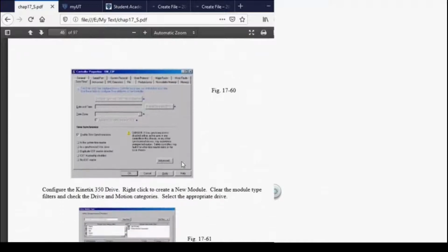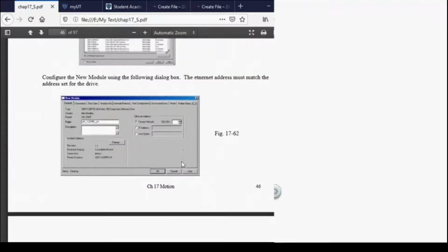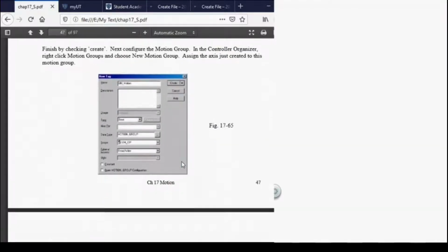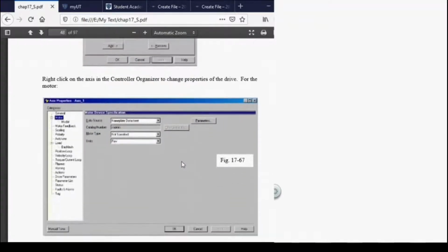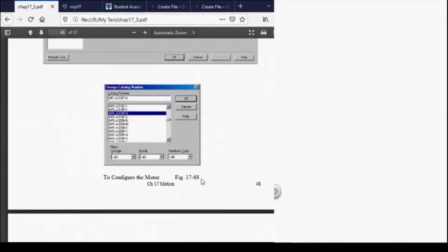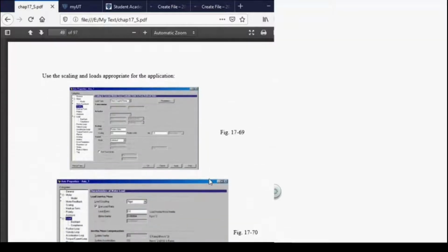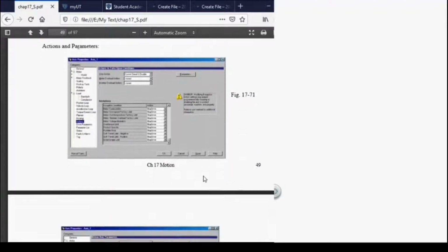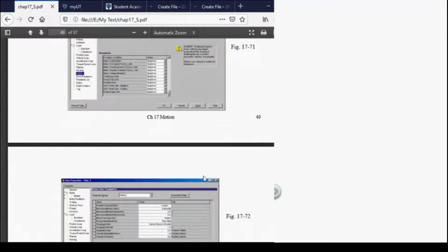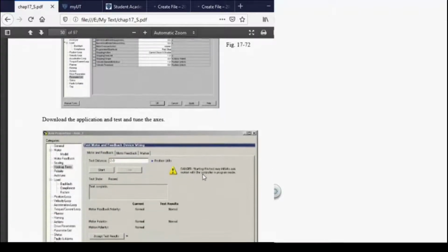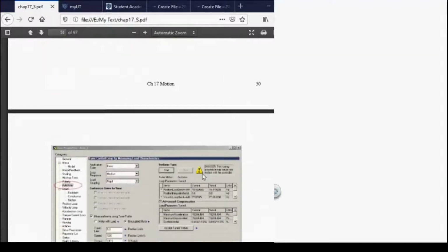Again, this is the commissioning portion of the Allen-Bradley. The Allen-Bradley does not have the switches on the top like the Siemens does. So the little switches that you have for commissioning are not on this one. But this one is specific to a motor, and you buy the motor and you get all the files with that motor, and that's what gives you the things to put in these various commissioning tables.